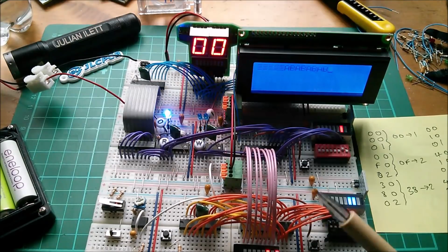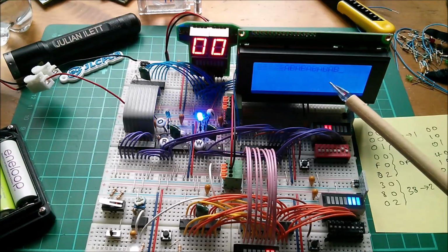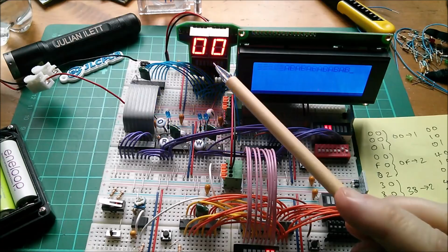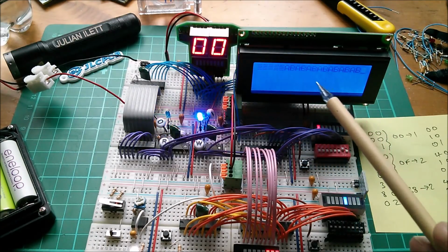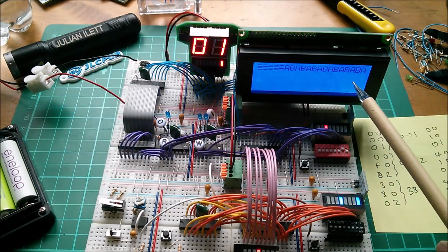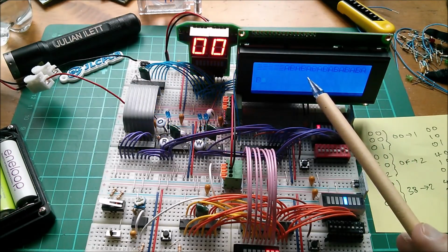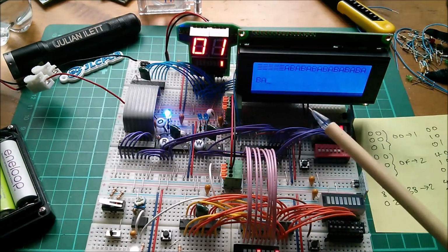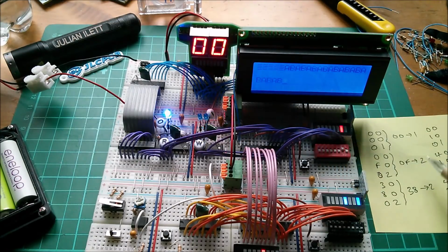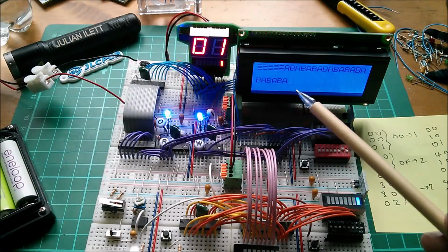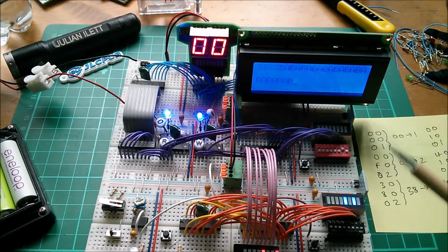In fact, just before I do that, I've got this looping round doing my AB program, and you can see that although every time it loops around it goes back into command mode and sets this to flashing cursor, that doesn't lose the cursor position. Got some funny contrast effects happening when it's in command mode, but it's continuously writing AB to the display very slowly, but then it takes a lot of instructions to actually get all this data across.